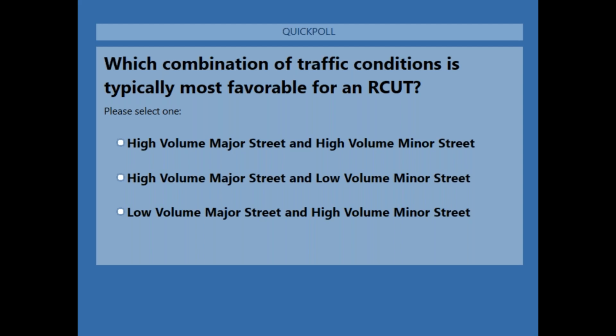Okay, and what is the average reduction in the number of signal phases with an R-CUT? Great. So I'm going to talk about how the R-CUT typically gets us down to a 2-phase signal, which is far superior to the multi-phase if we're providing protected left turns.